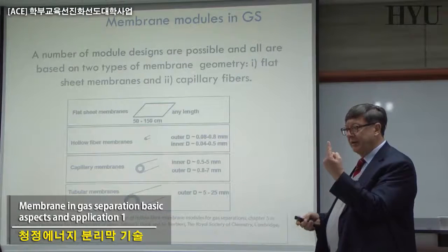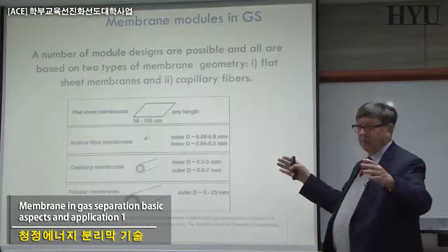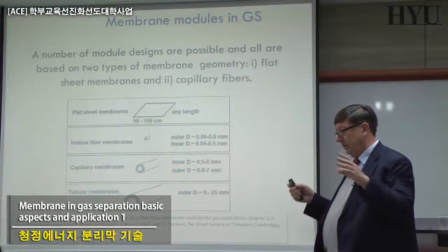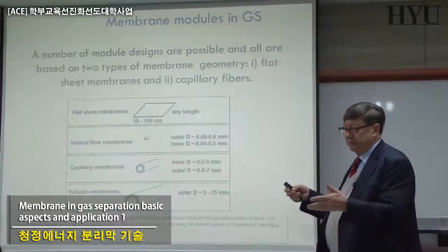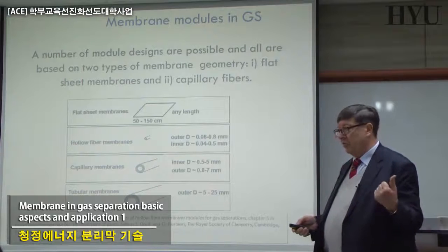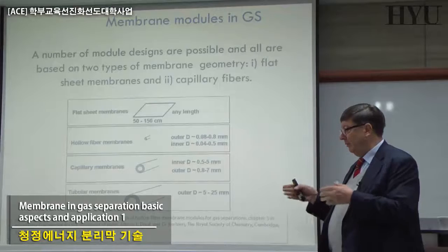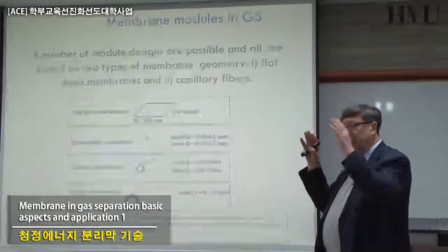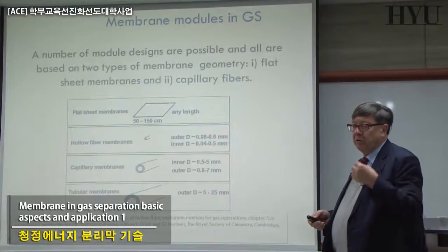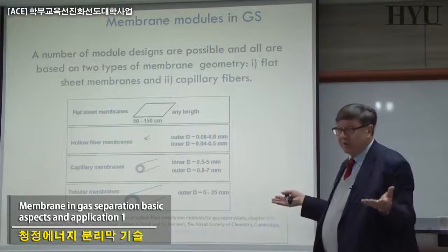By the way, you will never use membranes alone, you always have a module. Module means the assembling of your flat sheet or tubular or capillary, etc. Normally you don't handle membranes, you need the module. In reverse osmosis, when you want to handle the system, you can have modules in parallel or in series, depending on the overall capacity of the plant, but what you have to be able to do is reproduce, sometimes, 30,000 modules.